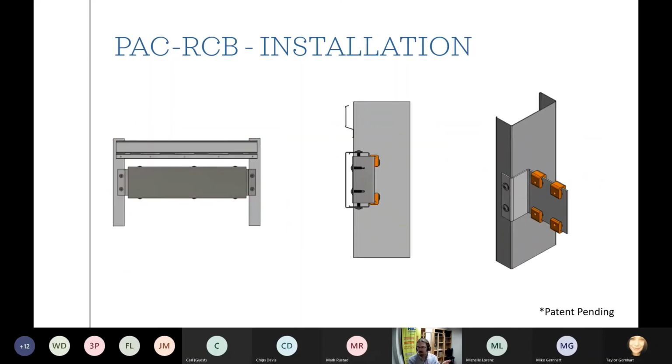Here are those drawings for steel studs. So you can see in the middle here how we've got the track and the stud nested together to make this box beam, that they get screwed together and then screwed in from the back, just like the wood 2x6 does.